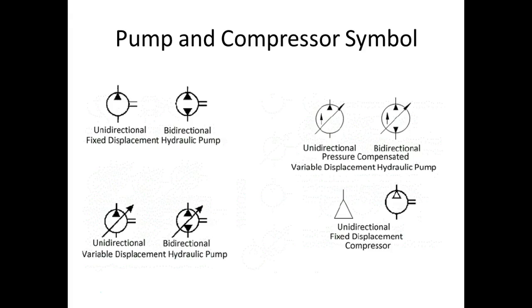So notice the difference between compressors and motors. So motors, the arrow is pointing in. From your compressors and your pump, the arrow is pointing out, right? If we got arrows pointing out on the bottom and the top, what does it mean? It's bidirectional, so it's actually vertical. If we have an arrow going through it, what does that mean? It's variable. Everybody okay? Hydraulics, the arrowhead is colored in. Pneumatics, the arrowhead is what? Open.